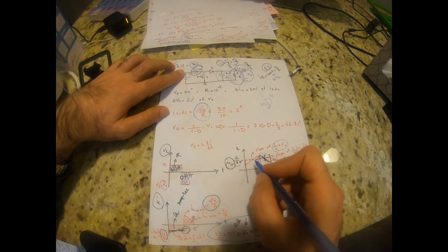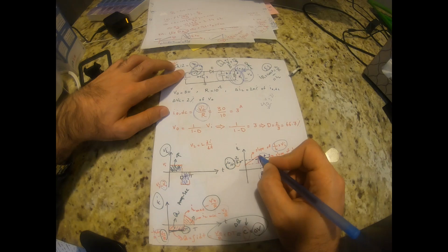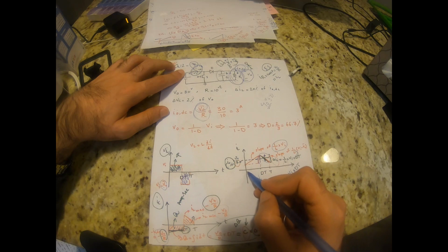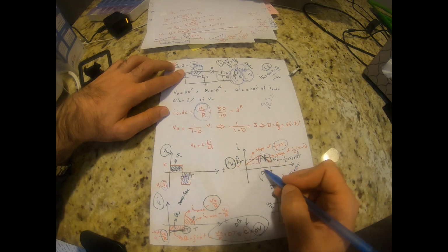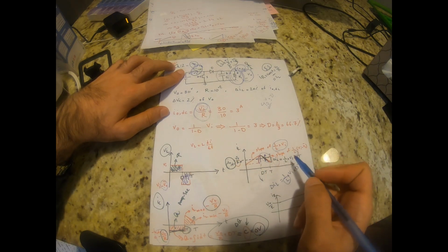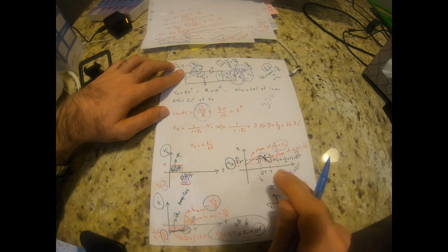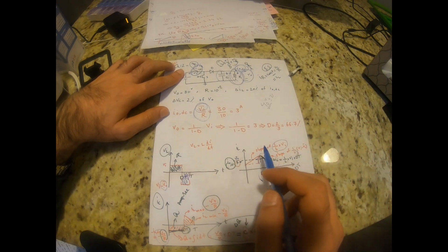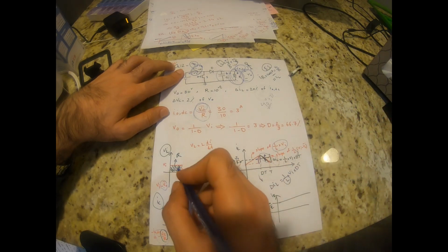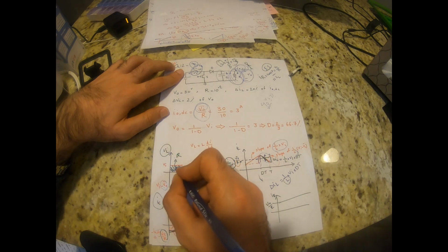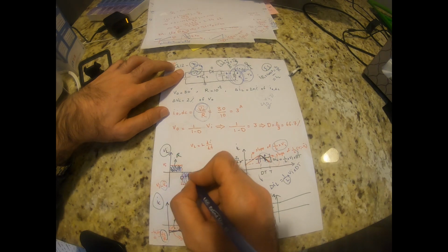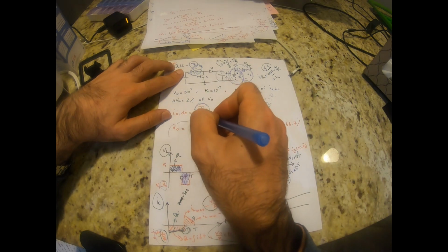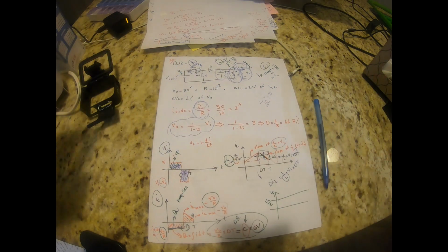You can actually calculate what this value is, once through this line, once through this line. It's going to be 1 over L times VI times dt, or 1 over L times VI minus VO times 1 minus dt. These have to be equal. You can also write the same equation by the volt-second balance, making these two areas equal. And based on that, we found this relationship between output and input voltage.